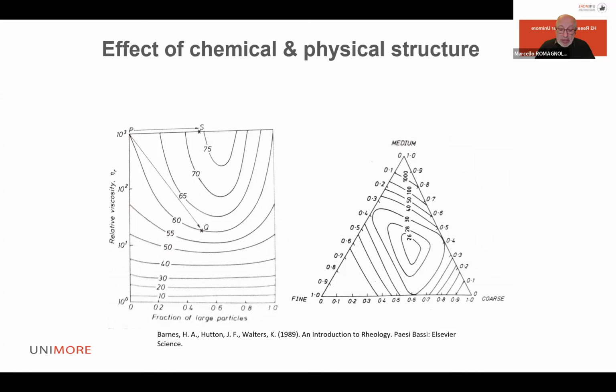In general, a broader and more optimized distribution, for example bimodal or polydisperse, allows smaller particles to fill the space between large ones. High packing density means greater free water lubricating the flow, and this permits obtaining lower viscosity.